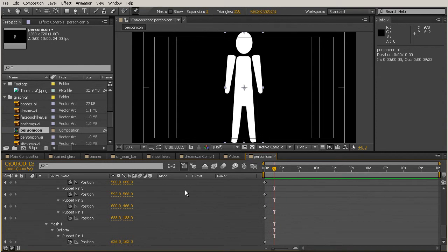And now I want to grab those points and move him so we can create a small animation. So come up there and grab your selection tool. And if you want to get back to those puppet pins, because now that we don't have this selected anymore, you can see that we're not able to see those pins. You can just click on any of these keyframes and it's going to bring those pins back onto your object.